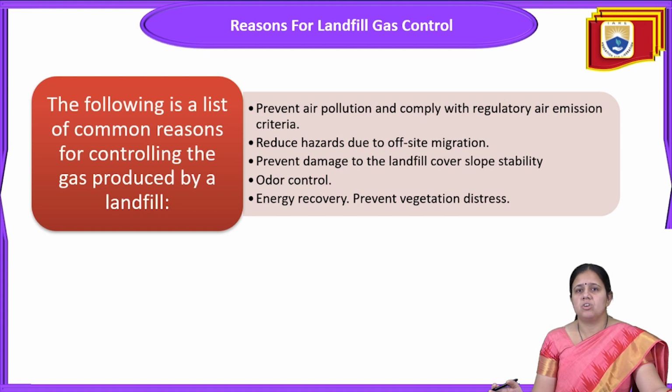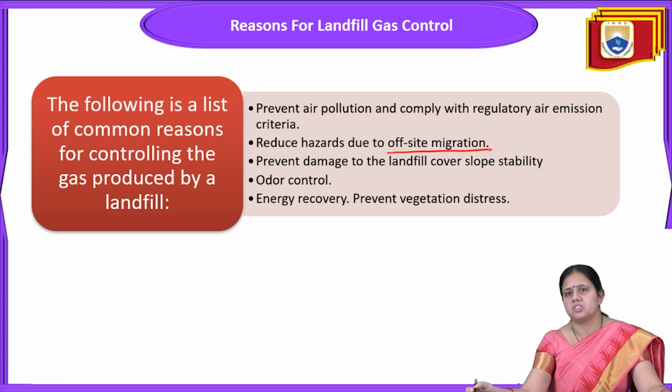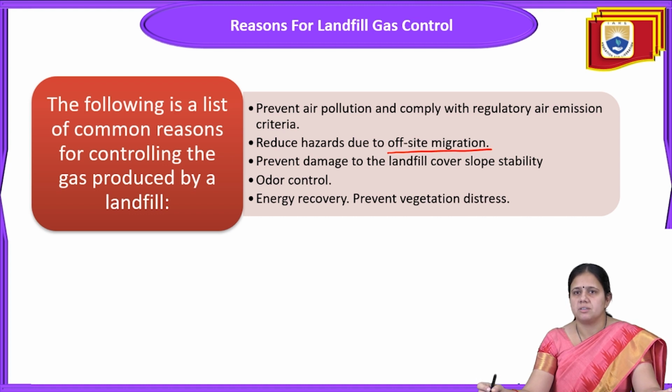And for some of the reasons for controlling gas produced by the landfill, we need to control the landfill to reduce the production of gases, because it is going to prevent air pollution and comply with regulatory air emission criteria, reduce hazards due to off-site migration, and prevent damage to the landfill cover slope stability.